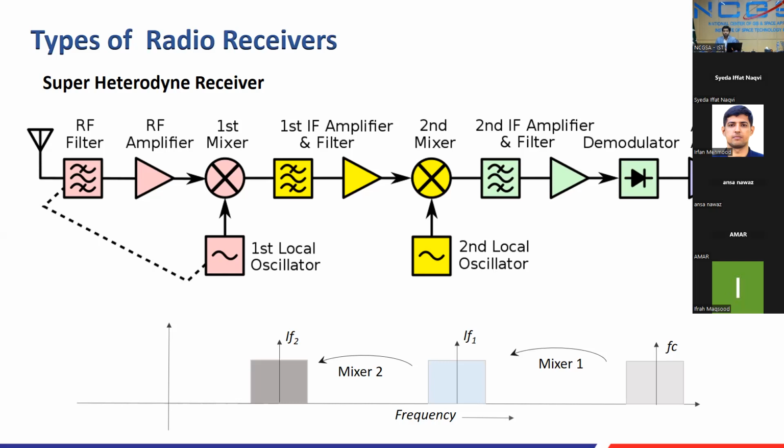In a heterodyne receiver, another aspect of any receiver is the distribution of gain. Any signal you want to receive, you want to amplify. A basic rule of thumb, or a better implementation approach, is that you usually don't put a lot of gain in the first stages. You only put components as low noise as possible before the first mixer. And between the two mixers, you put as much gain as needed to accommodate the conversion loss of the mixer.